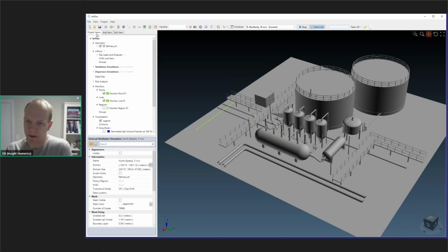We are just finalizing some aspects of that model for release, but the fire modeling capability will be released very shortly. And that will also plug into all of the existing capabilities of inFlux. We haven't covered it in detail today, but you can do risk-based analysis to get exceedance contours for gas concentration, for example. When we release the fire capabilities, you'll be able to get exceedance contours for radiation intensity, which you can then use for PFP design or any other application that needs a combustion model.